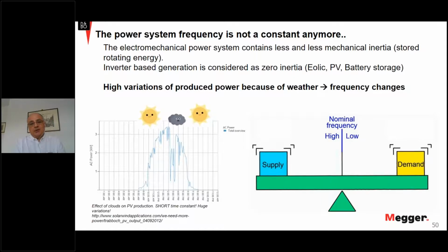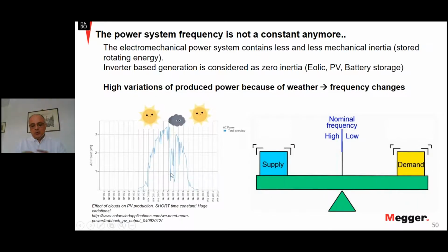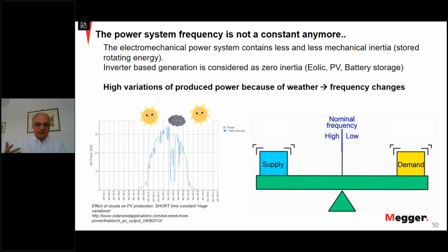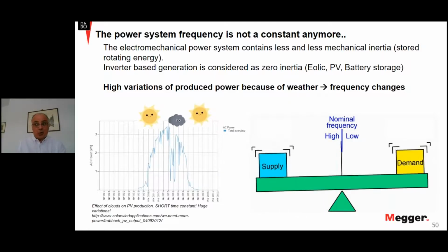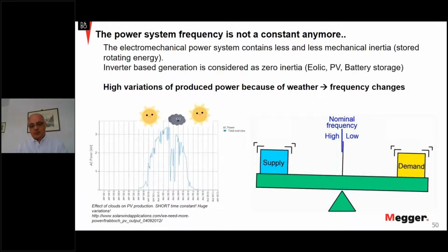The new renewable generation is also affected by weather. So in a few minutes, I can lose one complete city of solar panels, and in another few minutes, they come back. So I cannot shut off and shut on all the loads only because I have a cloud over Stockholm. So all of this means that the system must react, must talk together as much as possible, as soon as possible, and try to counteract this even by putting in some energy, for example, with batteries, etc.